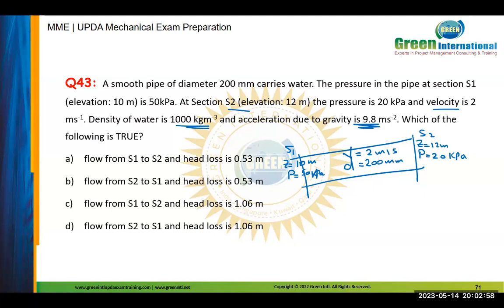One point: some engineers tell me the flow for sure is going from the high level to the low level. But if you check between high level and low level, you will find the pressure is in the opposite direction of the Z. Going to the numbers, you can decide which is dominant here, which affects more: the different elevation or the different pressure.